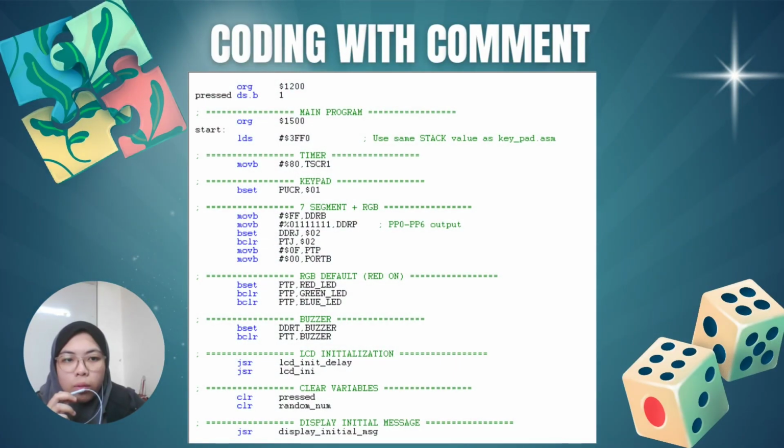Next, we go to the system initialization, which is the main program. The program starts by setting the stack pointer to ensure proper subroutine and interrupt handling. The timer module is enabled for delay and timing operation. Keypad pull-up registers are activated to ensure stable key detection. The 7-segment display and RGB LED pins are set as output. The red LED is turned on by default to indicate the system is in idle state. The buzzer is set as output and kept off during the startup.